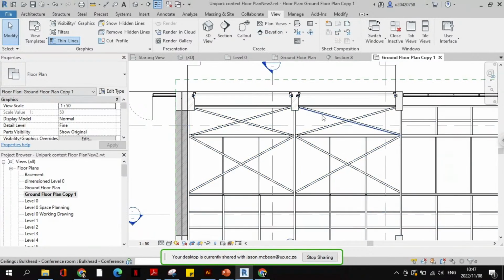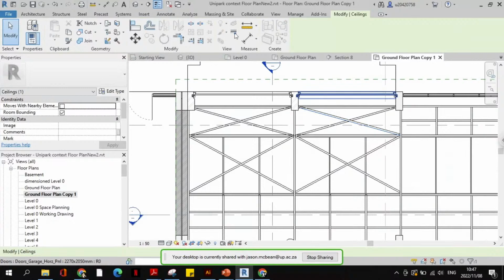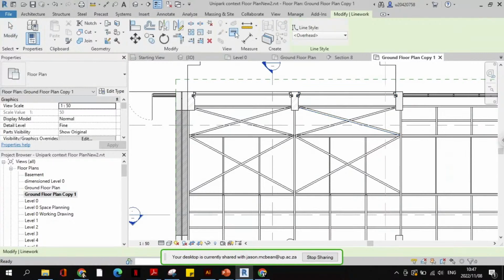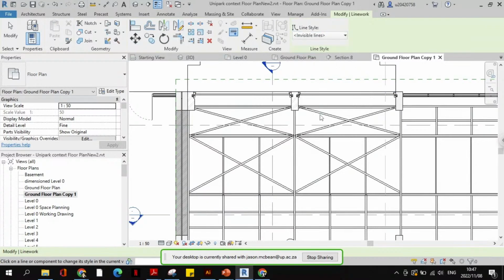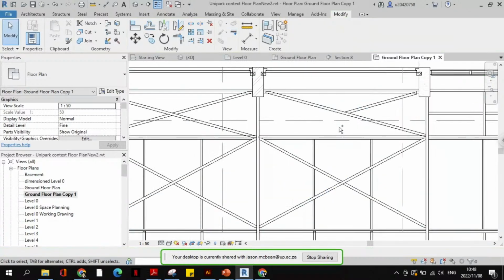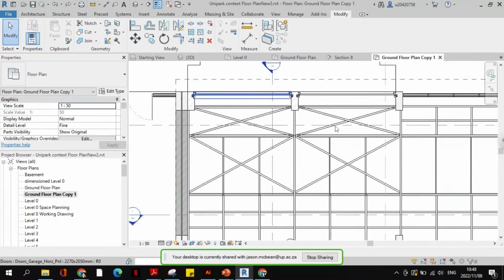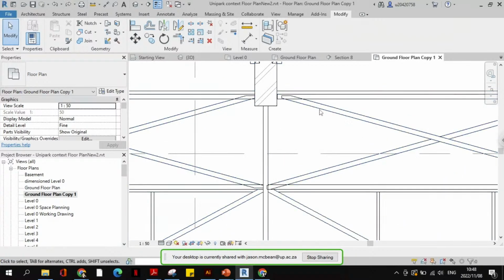Let me just tab. Oh, there it is. So you can overwrite the line work to be invisible. Invisible lines. So guess what happens if I click that? Watch. Ta-da. So you can quickly neaten up these little bits and then draft in what you need.